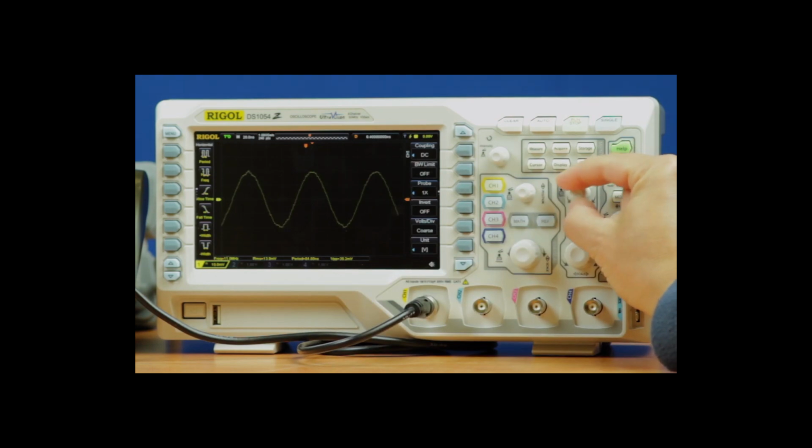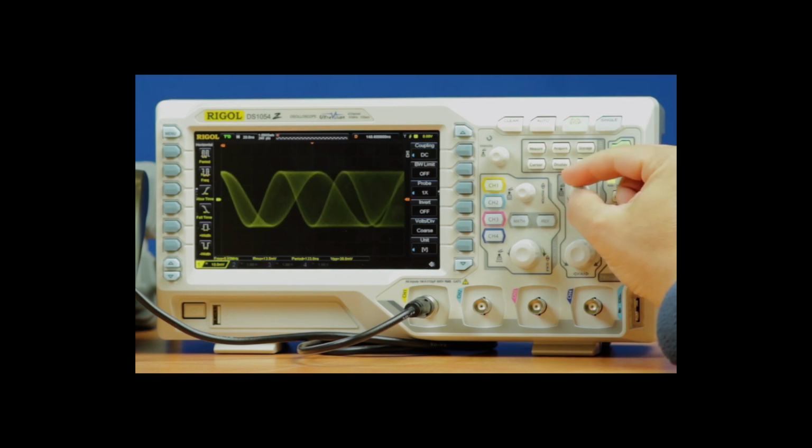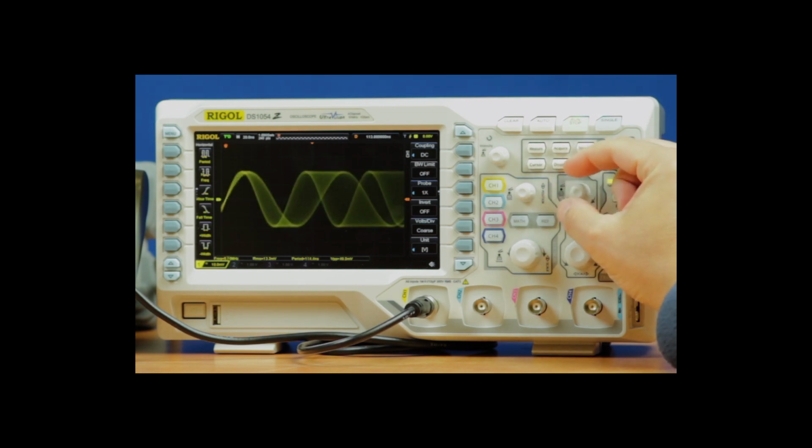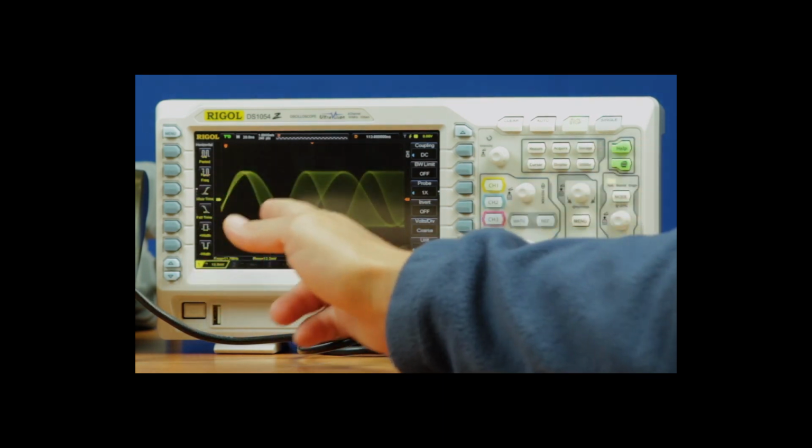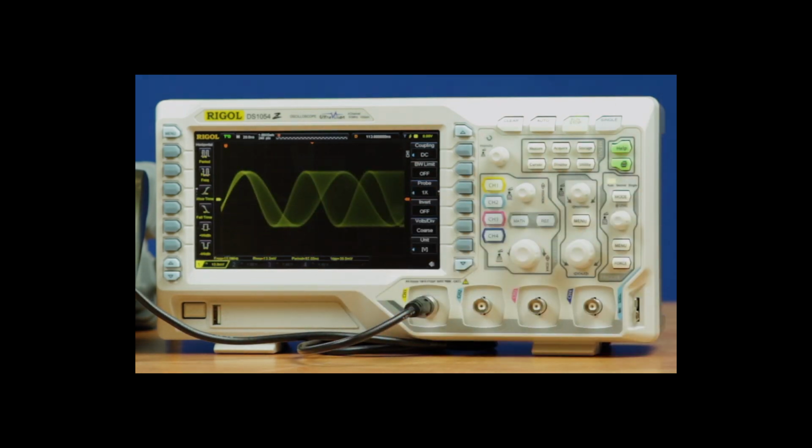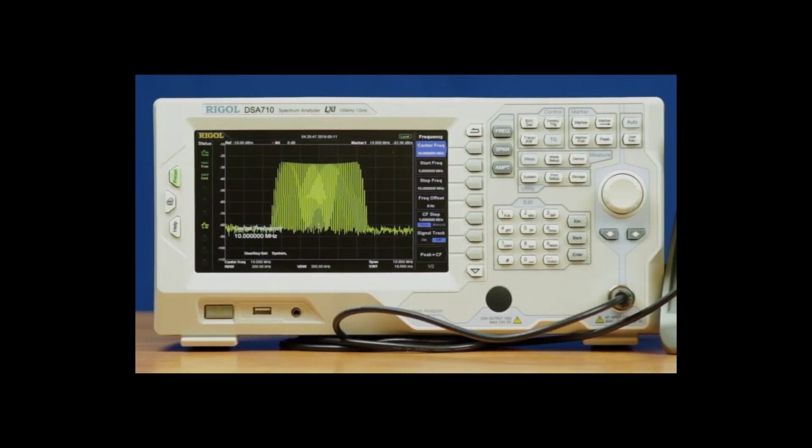If we move that trigger point to the left of the screen, now we can see as you move it over in waves, you get more and more discrepancy as the frequency is changing from shorter frequencies to longer frequencies. We see the same thing illustrated on the spectrum analyzer on the left. Here we can see how the frequency is quickly moving, about half the screen width, from about 8 megahertz to 10 megahertz. Actually 8 to 12 megahertz, centered around that 10 megahertz in the middle.